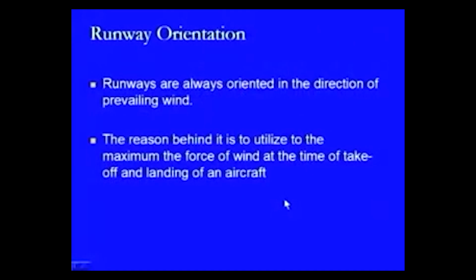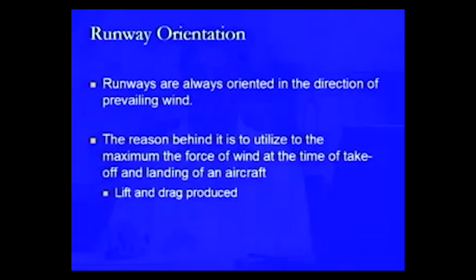So, that is what is important as far as the orientation of runway is concerned. The reason is that we are looking to utilize the maximum force of the wind at the time of takeoff and landing of any aircraft, in terms of lift and drag produced.